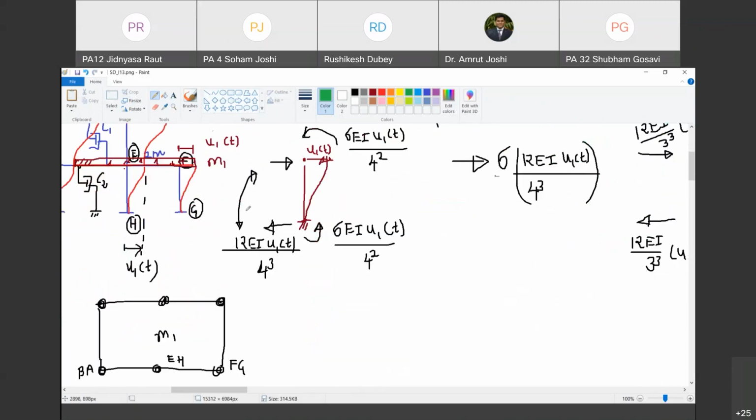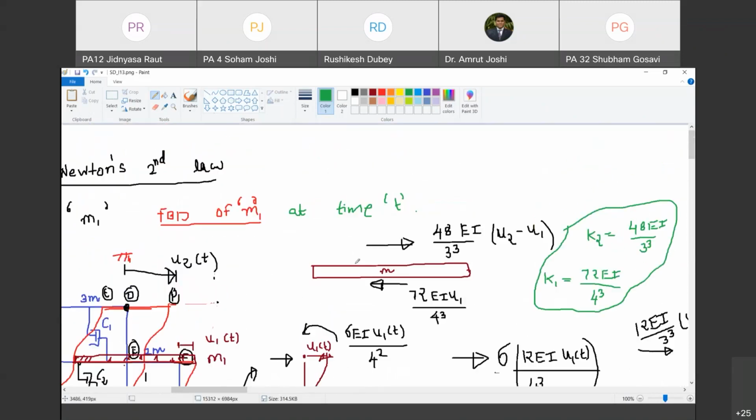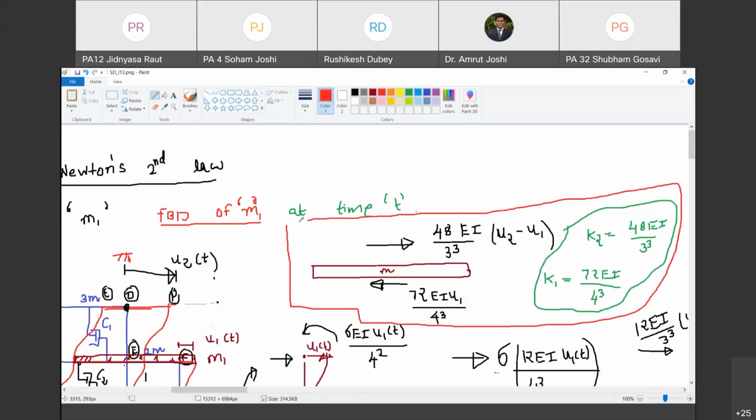देखो हमने ये सब जो बकवास की है बाकी के आजू बाजू की, that is for this free body diagram. So जो free body diagram सबसे important है उसको मैं box कर देता हूँ. You have to understand that this is what we are trying to do. Happy? Yes, sir. ये free body diagram complete है क्या? वो बोलो. No. When you draw a free body diagram of an accelerating object, you also show the acceleration. Are you with me? Yes, sir.